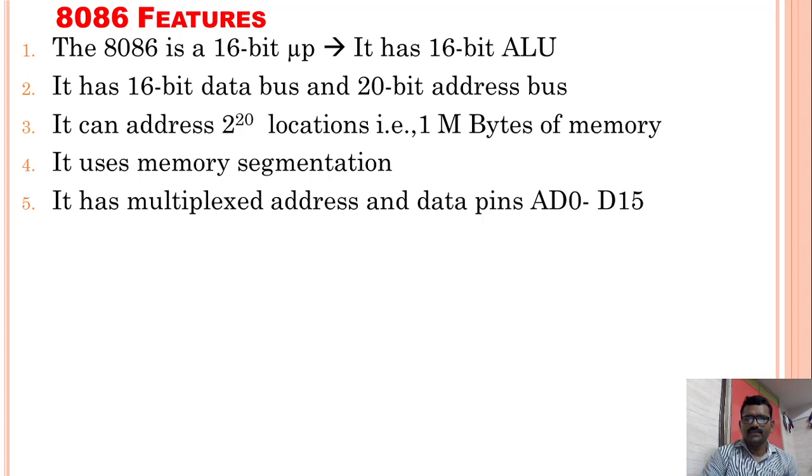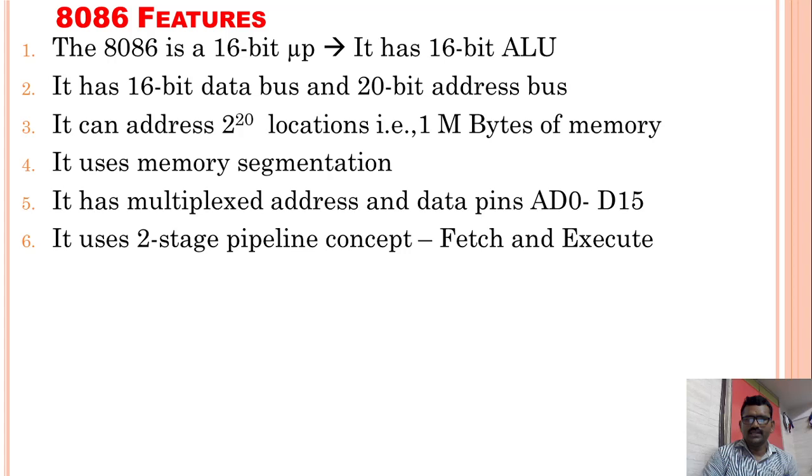And it has multiplexed address and data pins AD0 to AD15. With this, the number of pins per IC will be reduced. And it uses two-stage pipelining. The two stages are fetch and execute.